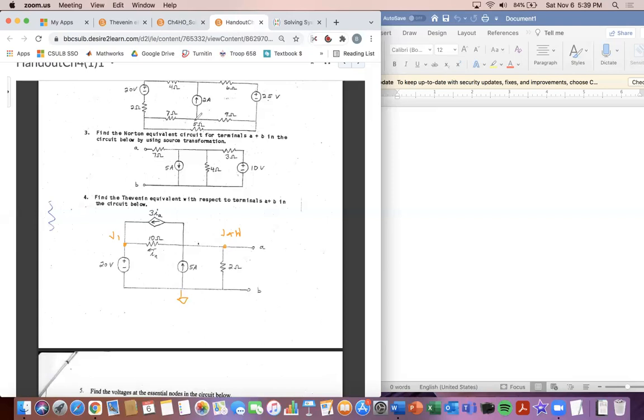And let me walk you through how you're going to form all those equations because it can be a little weird at first. So V1 we know is at the potential 20 volts. And so that's super nice that we know that now. So it gives us an easier time when we have to write the terms for V Thevenin. Let's write and see what we're going to get for other ones. So when I'm going to solve for this, let me do first the V Thevenin equation for that one here.